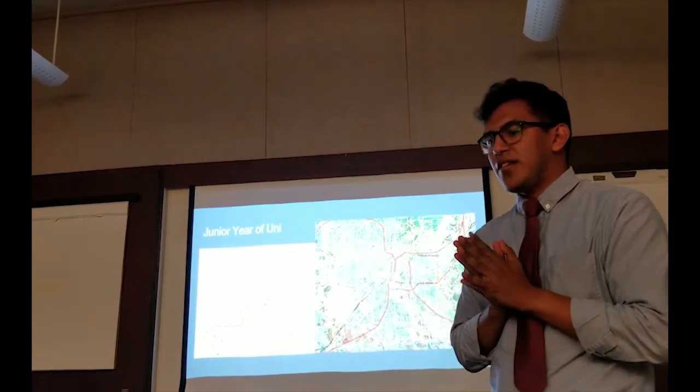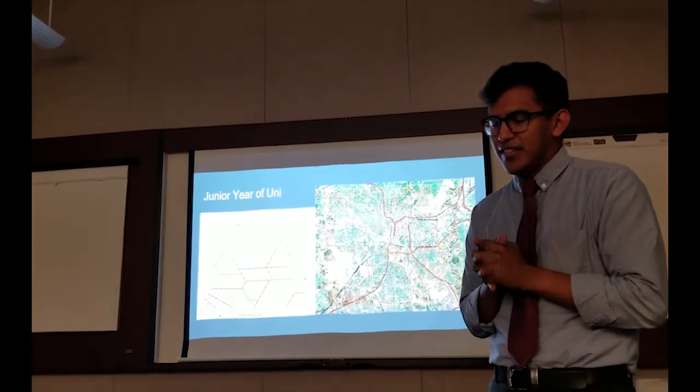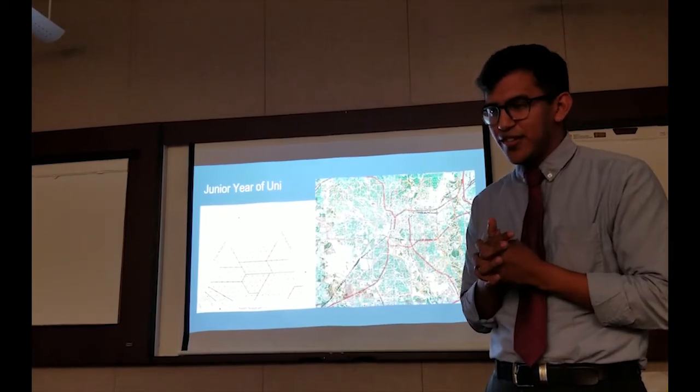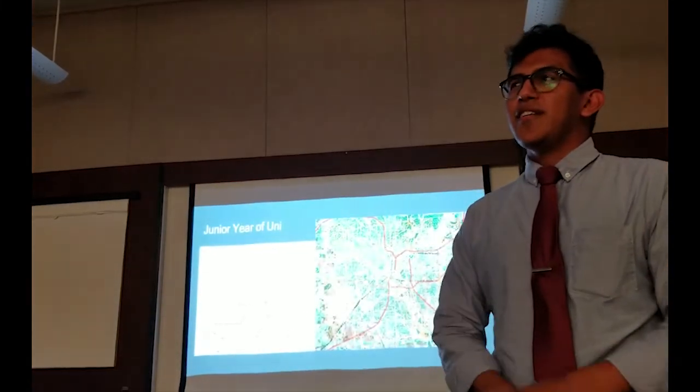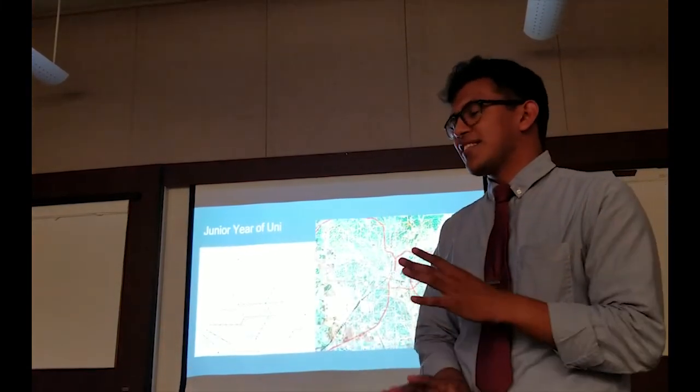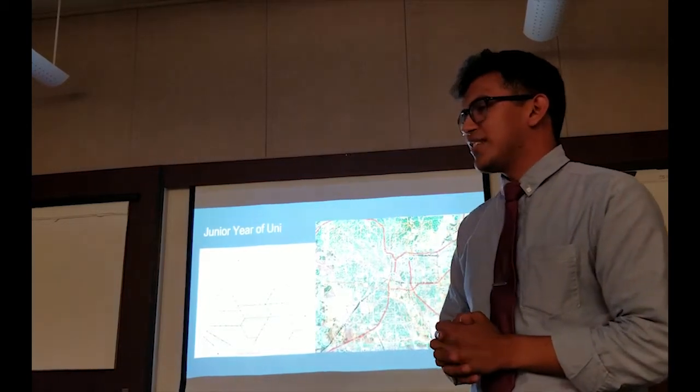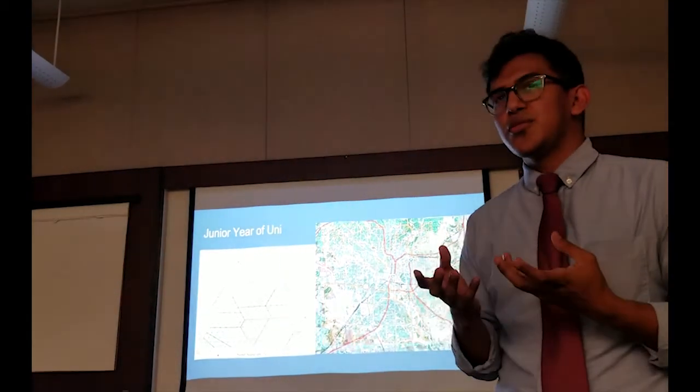Our house is built on concrete slab, and with my parents' limited experience, they trusted the homeowner and got inspections done, so, oh, it's fine. Well, the rain comes, and that's when you realize that clay holds water very well, which is fine at first. You'll notice after it rains that the ground soils kind of swell up. So the house will shift a bit, and you'll notice some of the doors start sticking or whatever the case may be.